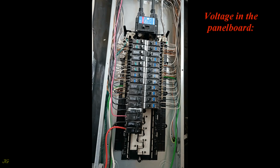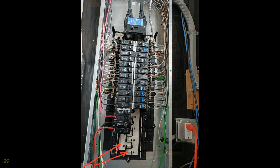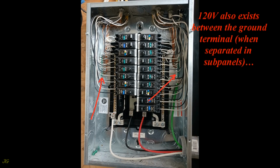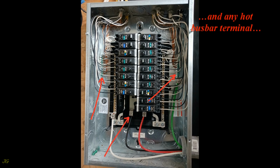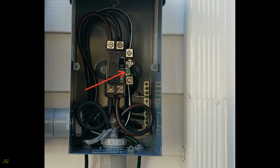Voltage in the panel board: 120 volts between the neutral terminal and any of the 2 hot busbar terminals. 240 volts between the 2 hot busbar terminals. 120 volts also exists between the ground terminal, when separated in subpanels, and any hot busbar terminal, because they are bonded together at the service disconnect.